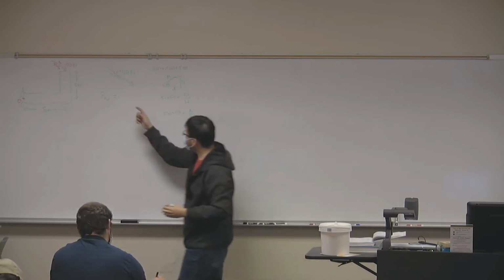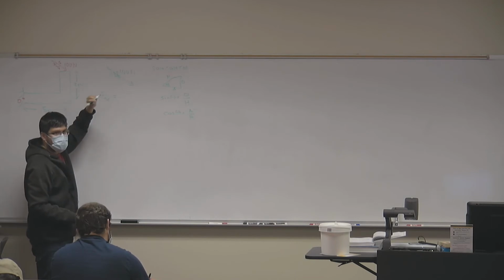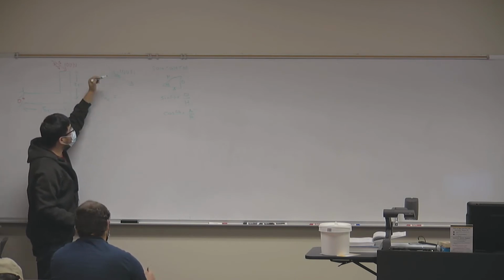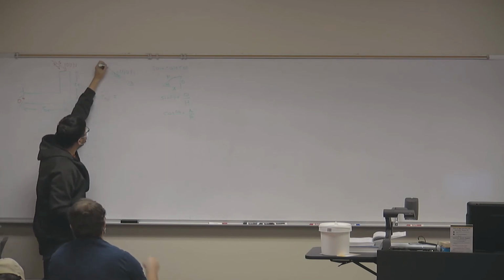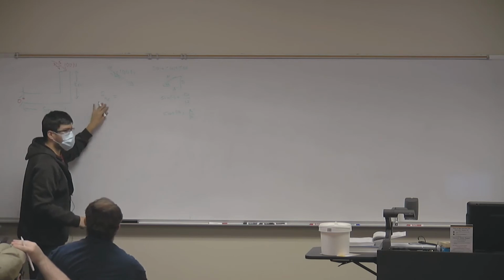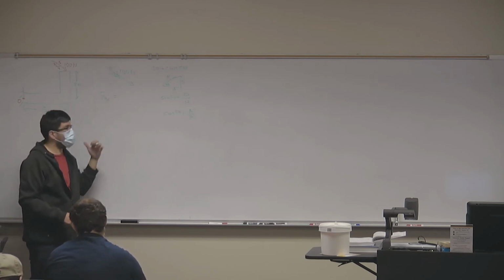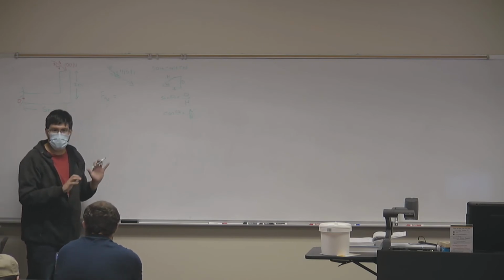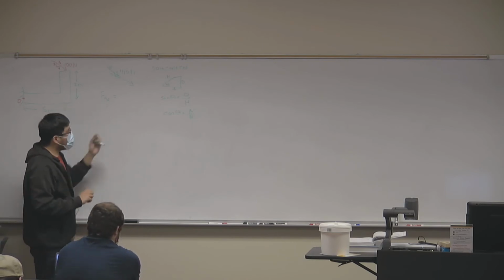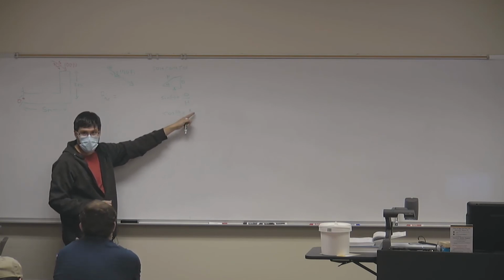So what I have here is a little triangle that gives me my slope of 3 to 4 to 5. And how can I find a relationship between my angle and my little triangle? Well, in the x direction, if my angle were from the horizontal, the x direction would be F cosine theta. And cosine of the angle is equal to the adjacent side over the hypotenuse.